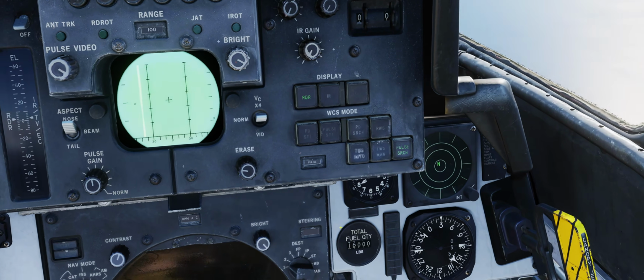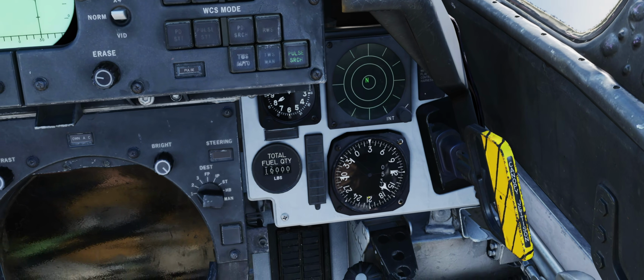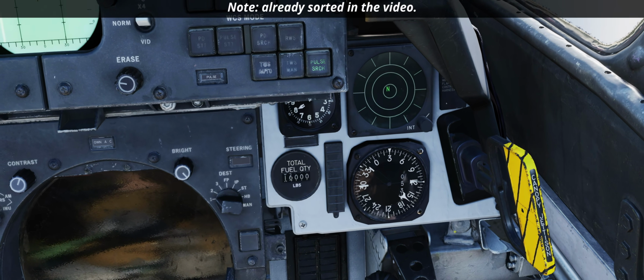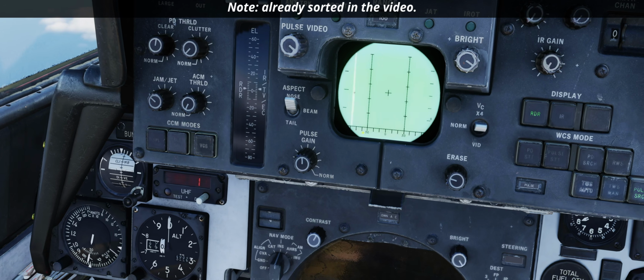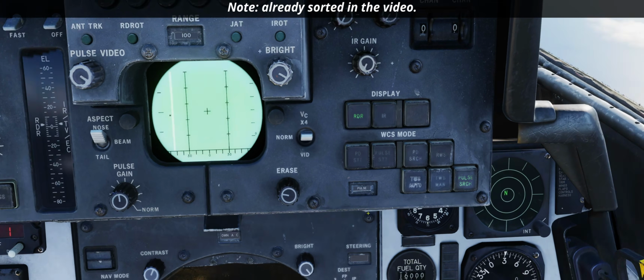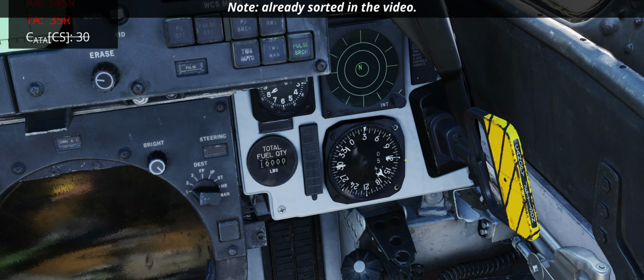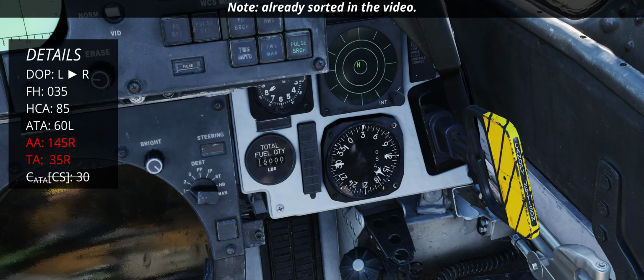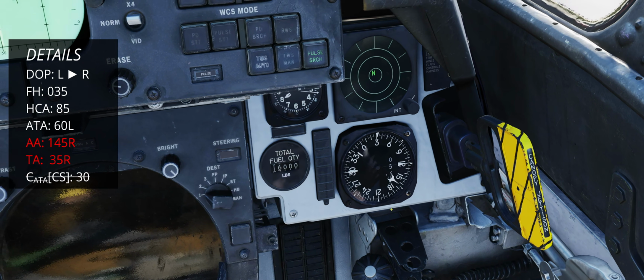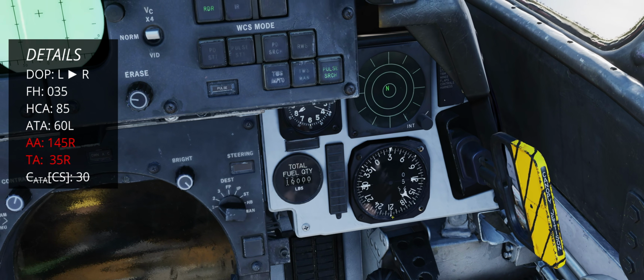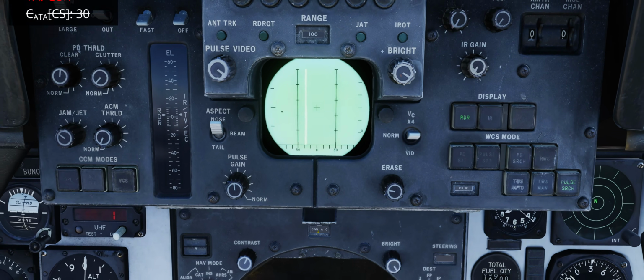Another thing we notice is how the higher bar illuminates the target, not the second. There is, therefore, a difference altitude-wise. Let's move to 1 bar and have a look. The target appears to be higher, and it is illuminated at about 1 degree at 50-55 nautical miles. This gives us a target flying between 5,000 and 10,000 feet higher than our Tomcat, and therefore 30,000 or 35,000 feet. Later, as we get closer, we can refine the approximation.